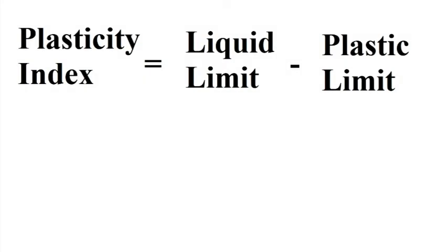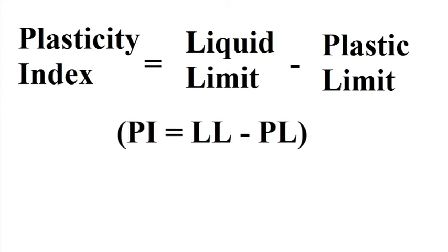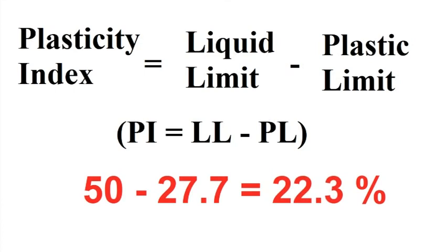The plasticity index is equal to the liquid limit minus the plastic limit. Calculate the plasticity index. Now that we have the liquid limit, plastic limit, and plasticity index, we have completed the Atterberg limits lab.